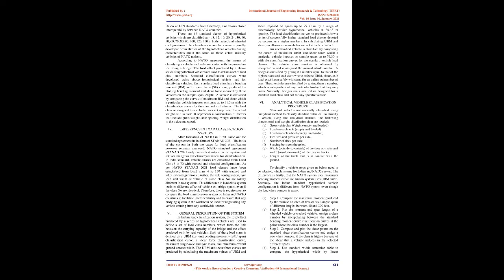Further, the axle configuration, tire load, and width of vehicle of same class number are totally different in the two systems. This difference in load class system leads to different effect of vehicle on bridge spans, even if the class numbers are identical. Therefore, there is a requirement to compare the load classification systems of India and NATO countries to facilitate interoperability and to ensure that any bridging system in the world can be used for negotiating any vehicle coming from any worldwide source. 5. General description of the system.